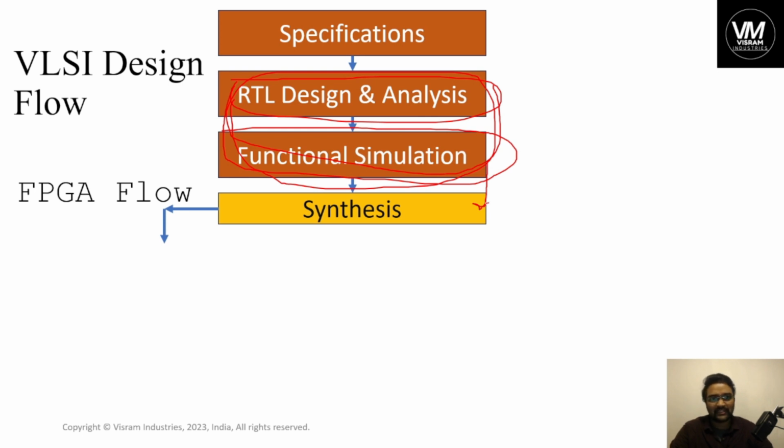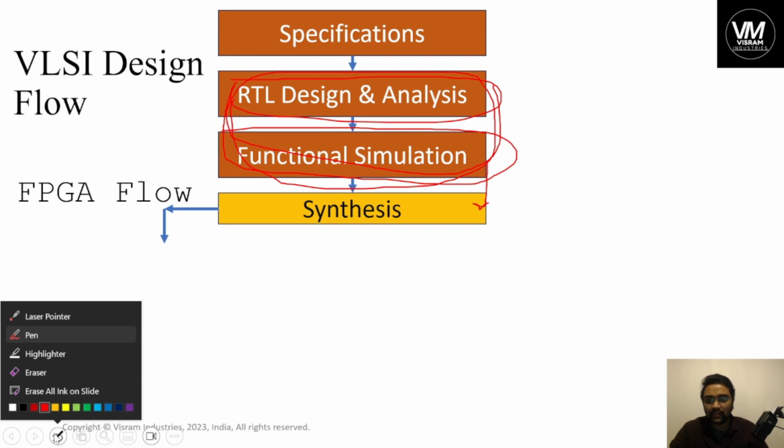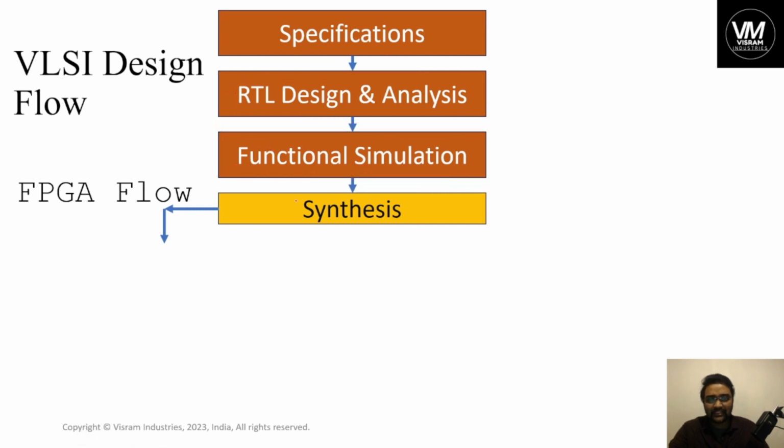As I told you yesterday, and I am repeating, this is about what to add as a logic gate, which OR gate technology you need to use, whether 3.3 volts or 5 volts, what type of flip-flops to use, and which lookup tables should be enabled. You have every element in a block, and whichever block you use, you should enable it. That type of enabling and assigning of the latest technology you are looking for in the design is made from the synthesis. Hence, the script you have written will be understood at the gate level.